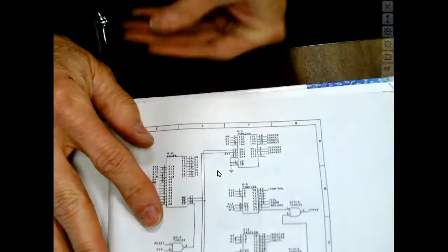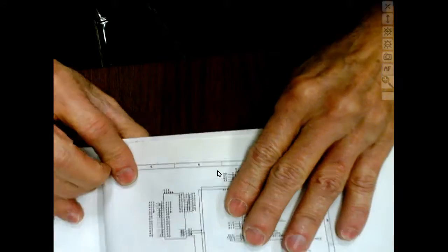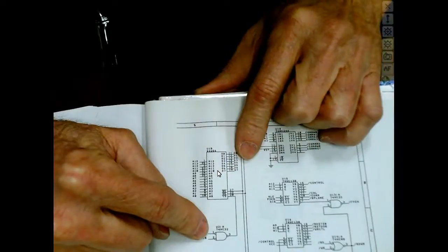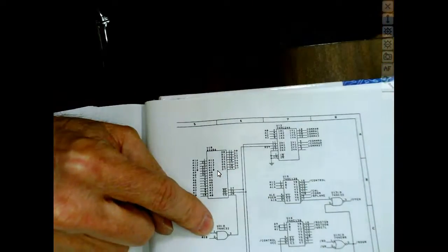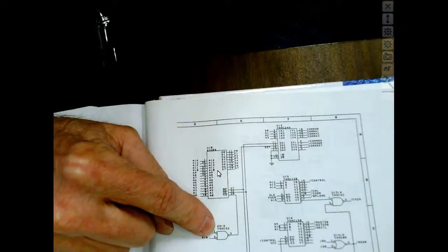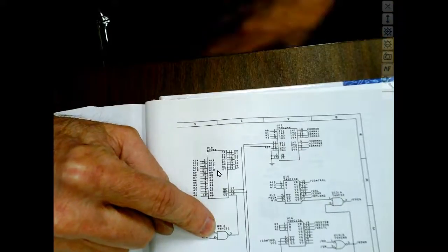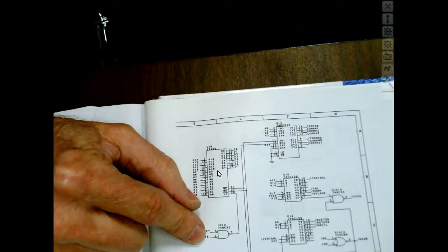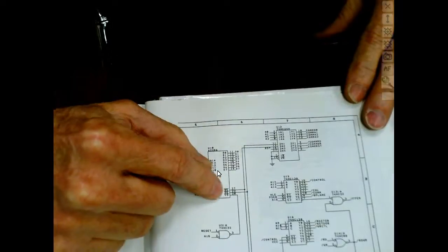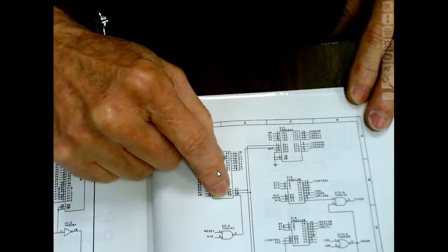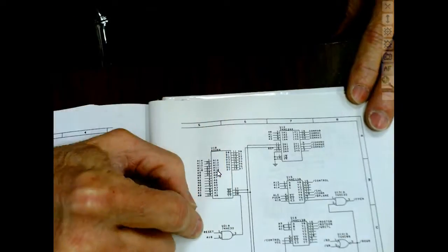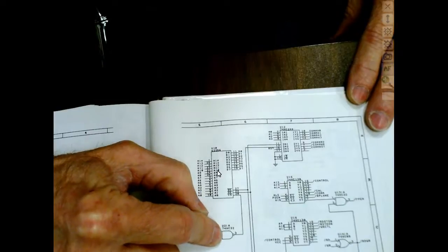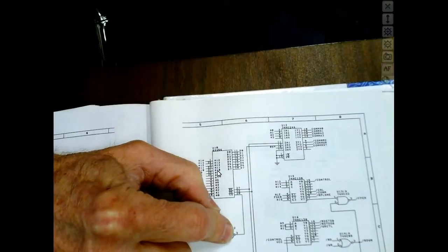I look over on the next page. So this is page 135. This right here is an OR gate. If I looked up a 7432, it's going to be an OR gate. But they don't have it drawn as an OR gate. They got it drawn as a negative AND, because this guy right here, this CS, is looking for a low. Well, what does it need to get a low? Well, it says all lows equal a low.